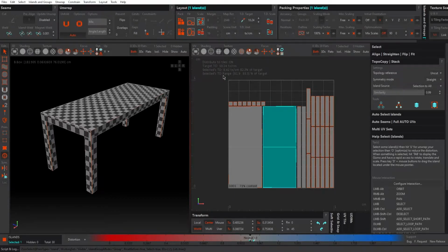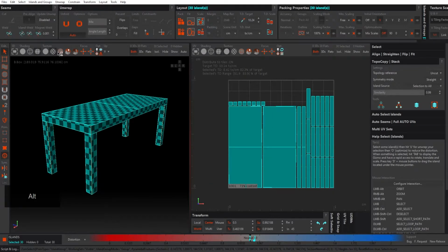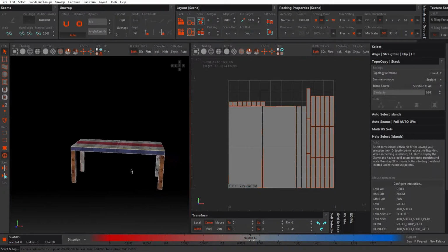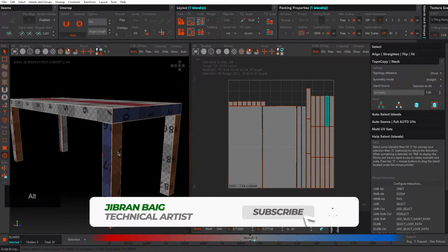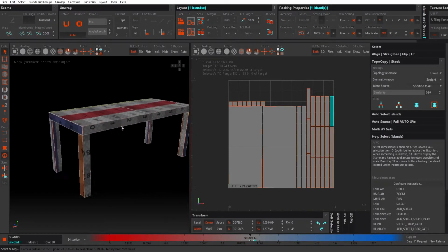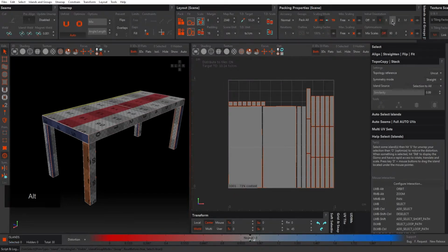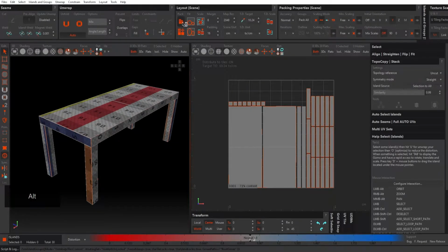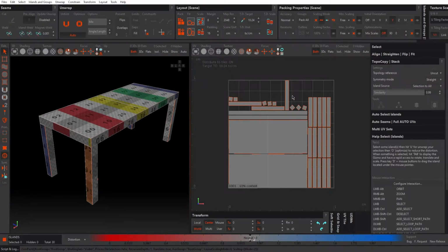The next thing would be to align these to the right direction. In this case, this is okay, and this one is not, this one is not. So we could, like I said, do it manually, or we could try to set up the initial orientation to the up Y world axis, and try to pack it again. And in many instances it can do a good job. We could try the packing accuracy, and we can up this to here and here, let it give RizomUV some more iterations.